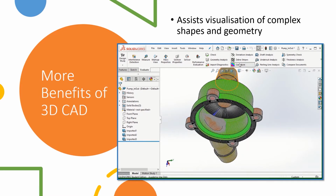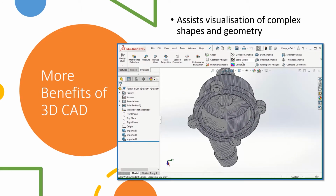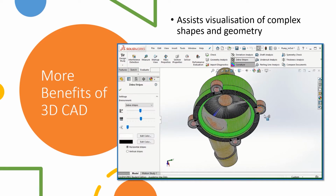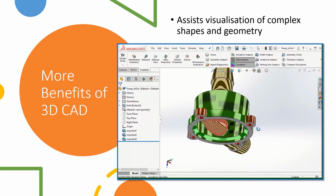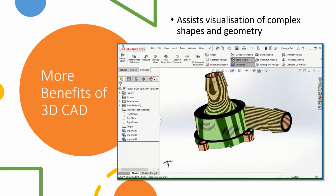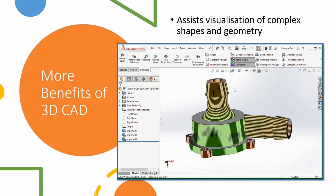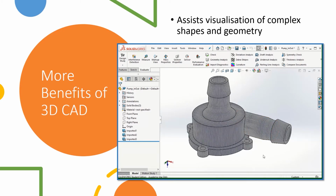So if I turn those off, you can't really see how that curvature is working. But if I turn both of these on, there we go, I've got the visualization on it now. I can see exactly what's going on with that bit of geometry. Nice and psychedelic, hey? So that's just a couple of ways that we can use the tools in SolidWorks to be able to view complex geometry in a little bit of a clearer manner than just a standardized view or a two-dimensional view.